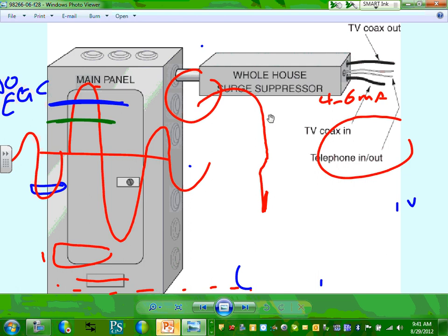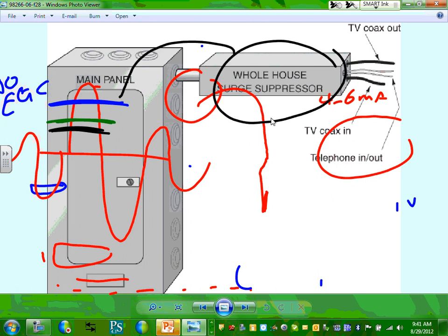And right at the receptacle level, it cuts the rest of it. So they use multiple levels of surge protective devices. If your building has a lot of electronic equipment, that's the perfect application for different levels. What you're looking at right now is level number 1, at the service. This level will be the receptacle we just looked at, the surge protective device receptacle.